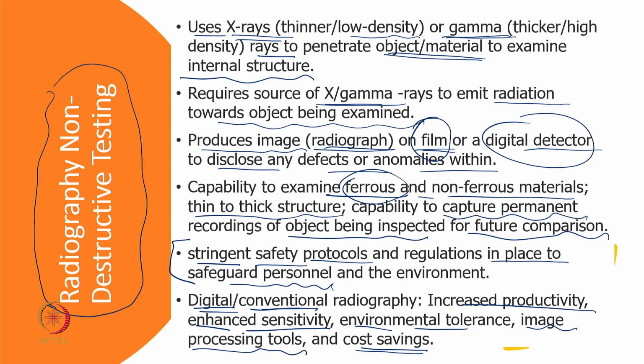Particularly, in one of the previous examples, we examined something like concrete which has iron material, which can also corrode, and there will be some failures in that. So for that purpose radiography will be a good option, or maybe can compete with other techniques. If we are able to find faults with another technique, we should not come to radiography, but if we are not, and we want much more reliable readings and predictions, then we should come to radiography.